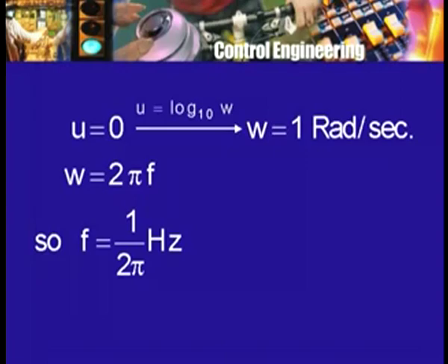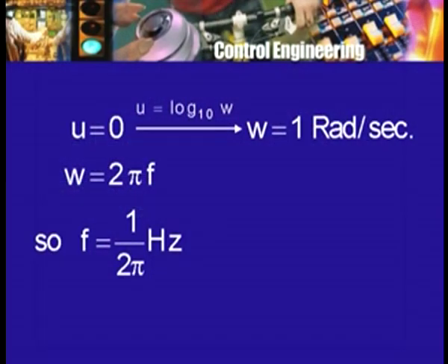Now, depending on how you are plotting the graph, whether you are plotting it in terms of hertz, that is actual cycles per second frequency as such, or you are plotting in terms of the corresponding angular velocity omega, which is 2 pi f, and remember we have to substitute s by omega, not s by f. So, if you want to put f there, then you have to replace s by 2 pi f. So, accordingly then one may plot radians per second or hertz, that is cycles per second.